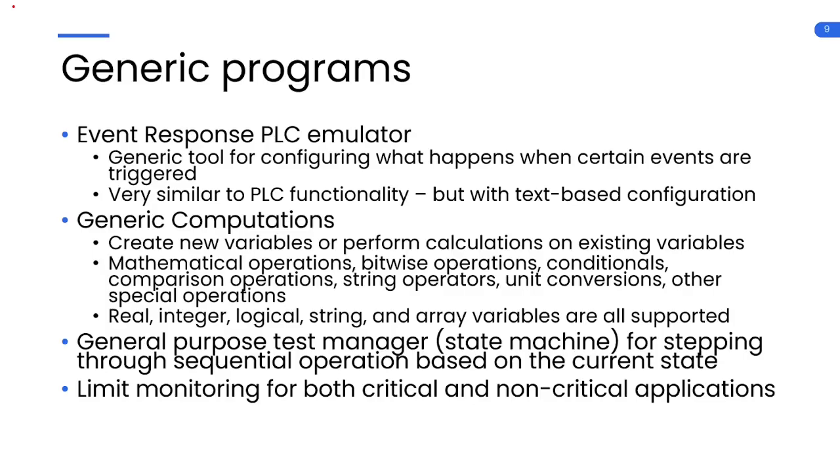You can, and sometimes there's a use case for that in event response, but in general, this is where if you've created your own event that's tied to, say, a digital input that's reading the status of a flame detector, you can configure this program that when that event goes off, you can configure other outputs. So from here, you can set variable values directly, you can launch scripts, you can set other events, you can do conditional checks that says if there's a flame detect and the engine's running, do this, but if the engine's not running, do that. The possibilities are kind of endless.